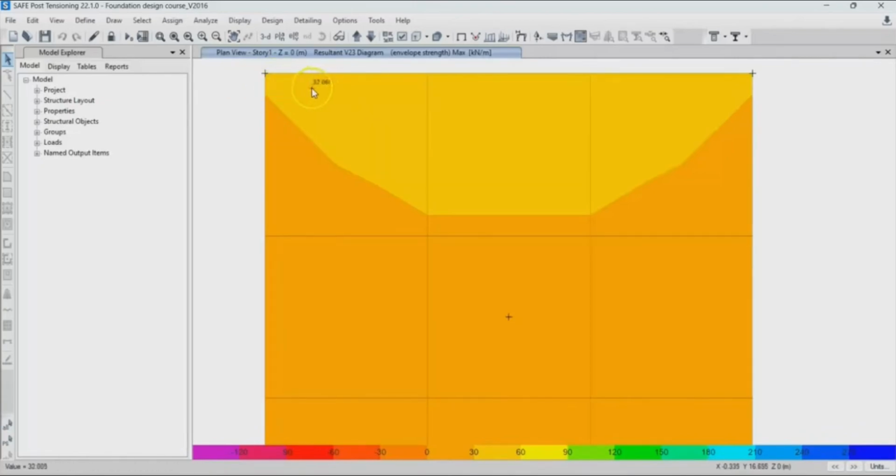We said we mesh the footing area to be 0.5 meter, right? So SAFE is going to look directly at this 0.5 meter grid and line. Okay, so what it does is, because this is calculated point by point, right? This finite element is calculated point by point.